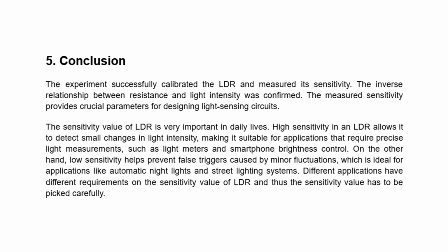High sensitivity in an LDR allows it to detect small changes in light intensity, making it suitable for applications that require precise light measurements such as light meters and smartphone brightness control. On the other hand, low sensitivity of an LDR also provides advantages in preventing false triggers caused by minor fluctuations, which is ideal for applications like automatic night lights and street lighting systems. Different applications have different requirements on the sensitivity value of the LDR, and the important thing is we need to select the correct sensitivity value for each of our applications in our daily lives.